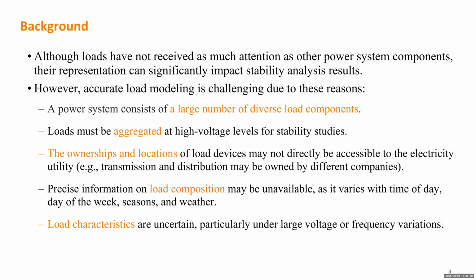And the data we use to model the loads usually are collected from normal conditions, right? But why do you need to do a stability study? Because you want to cover abnormal conditions, but you don't have enough abnormal condition data. You can only somehow predict what abnormal conditions can be. But the load model is pretty much based on normal condition data. So there are those challenges, which means we don't really have to model the load very accurately. And actually, it's not practical to do that.